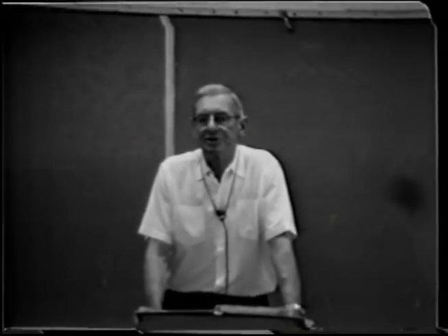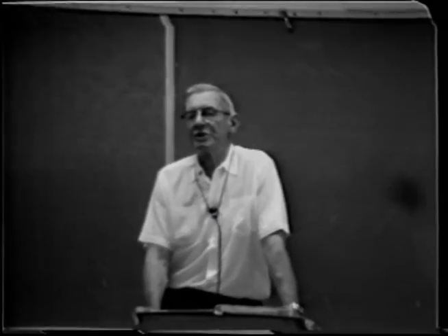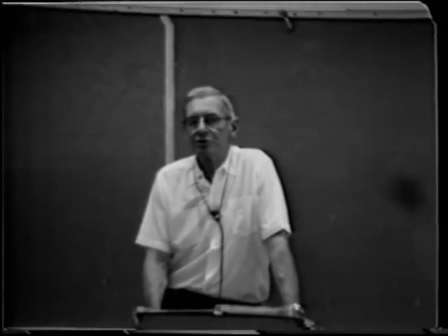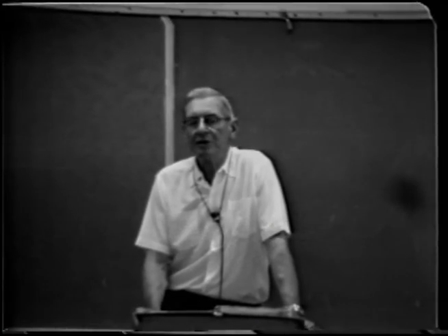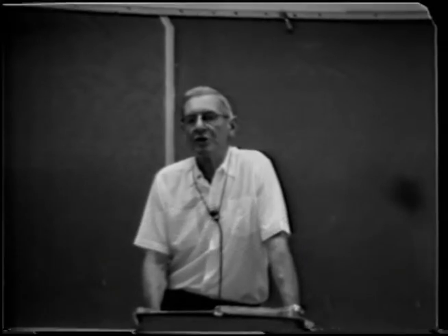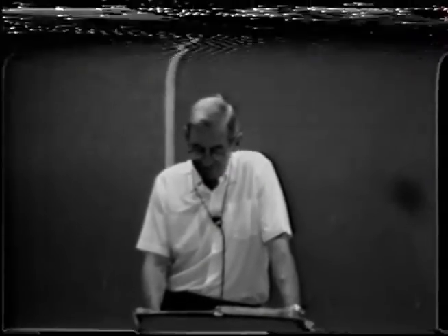Now, which is the best relationship to use? Low temperature, long time, or high temperature, short time? Well, predicated on the findings in the food industry, they have found, without exception, I think I'm safe in saying this, that the high temperature short time heating does the least damage to quality. So where you have an option, choose the high temperature short time relationship rather than the reverse.